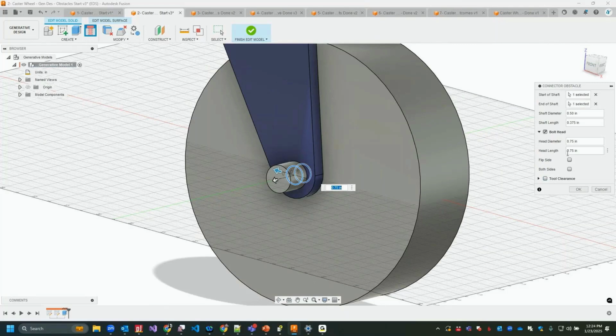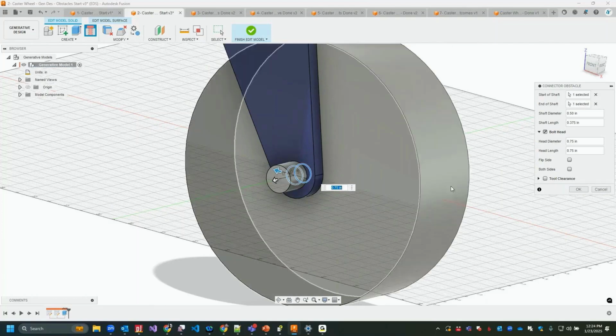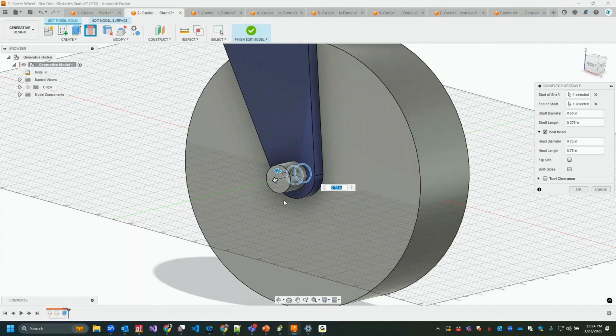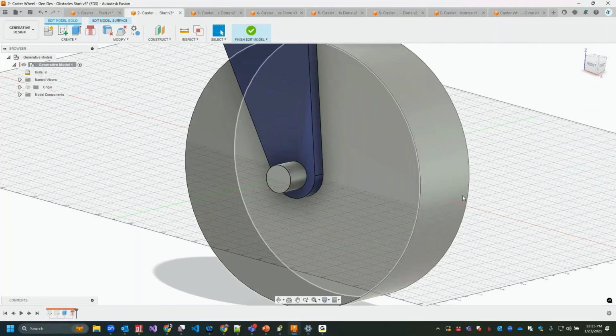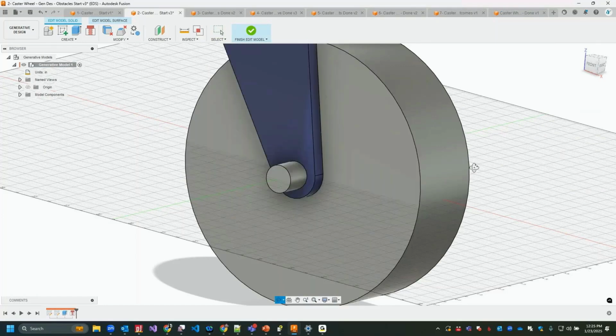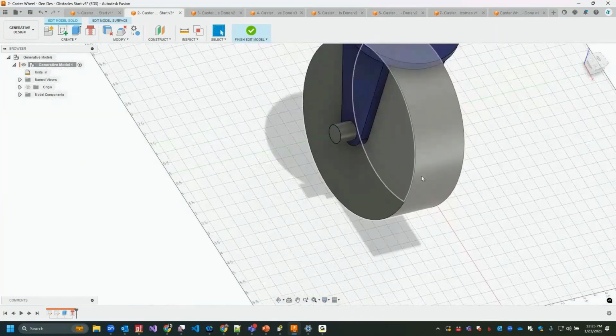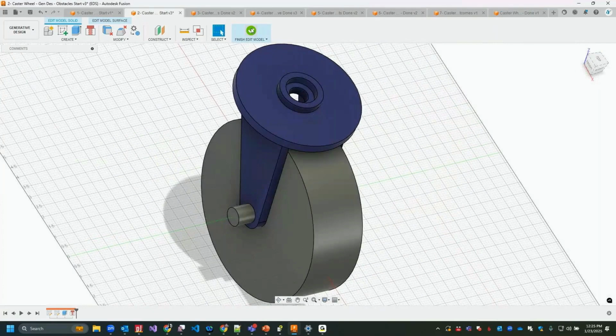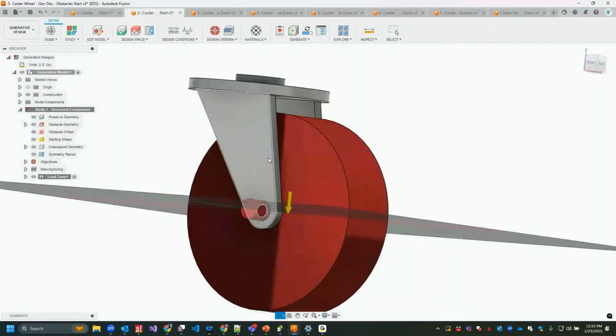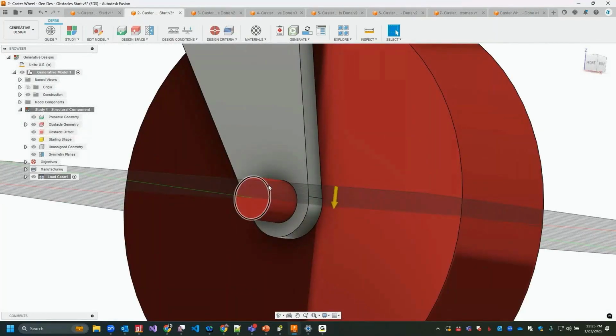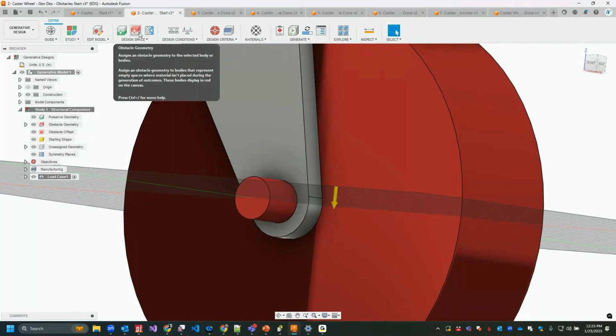With this, I can define whether we want some obstacle in there for the bolt to be able to fit, or the tool clearance to be able to fit a tool inside there so it doesn't grow into there, so we can fit that tool in. I can do it for that side. I can also do it for the other side. Okay. When I hit finish edit model there, you can see that since we're using a connector obstacle, it automatically takes that and sends that to the obstacle geometry.